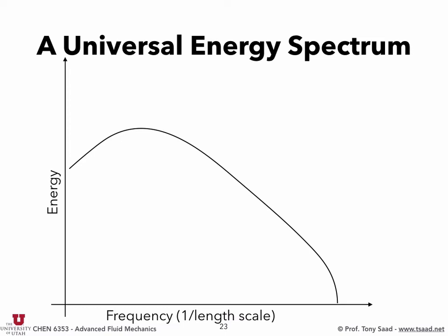And the large scales, think of this as like several times the size of your domain. And then you see over here, at this point, you have the largest energy. These are the eddies that contain the largest energies in your domain. They're on the order of the size of your domain over 2 or over 6. Those are the largest eddies that are contained in the flow. There's a lot of scaling for this in Kolmogorov's hypothesis. We can talk about this on Wednesday, hopefully. But then there's a point beyond which energy just continuously decays linearly on the log-log scale, and then is dissipated suddenly over here at these small scales. And that's a key signature of turbulence.